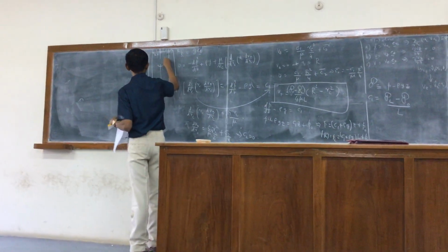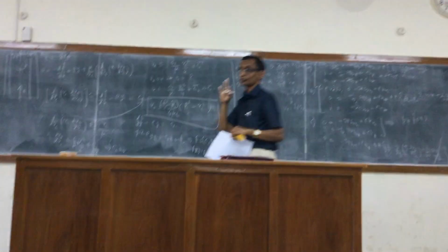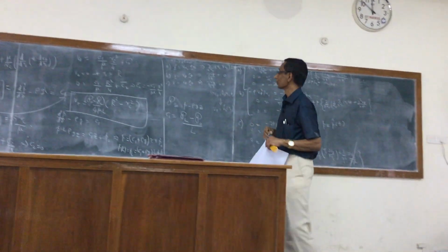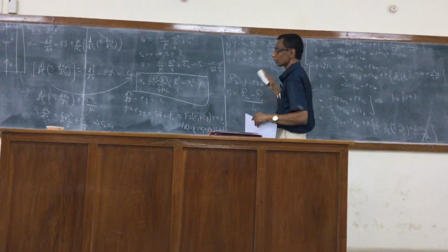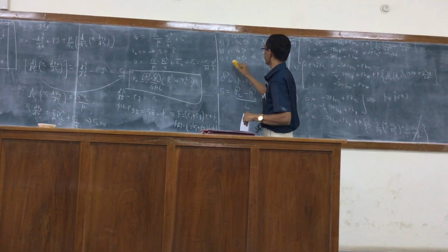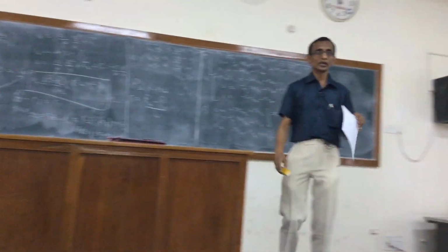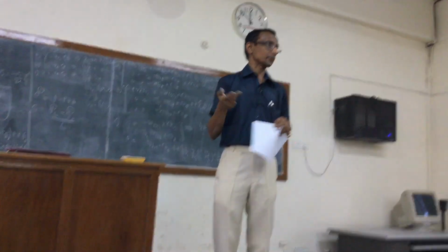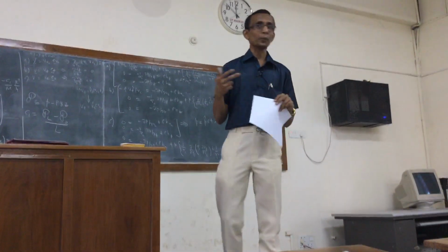So the rotational flow we assume to correspond to, this is not to be confused with the rotational flow that is commonly used where the curl of the velocity vector field is non-zero, but this is rotated. So it's assumed that this corresponds to the case B, and we can safely assume that the radial component and the z component will not be there. Right? This is a standard assumption. The dominating velocity component would be V phi.